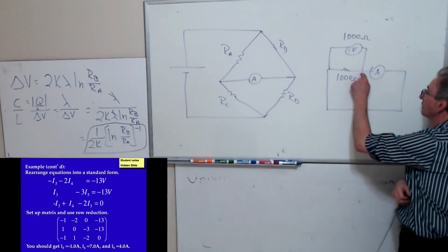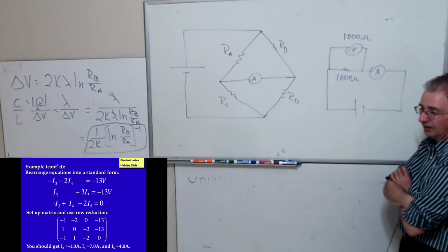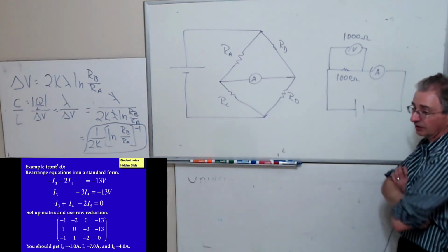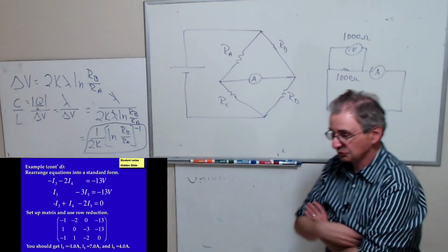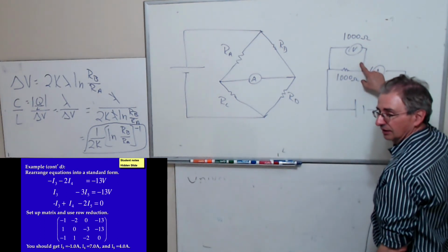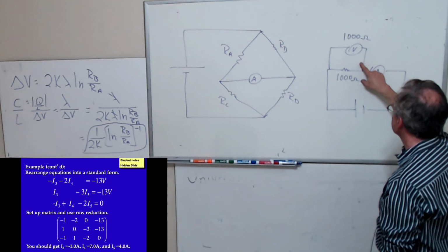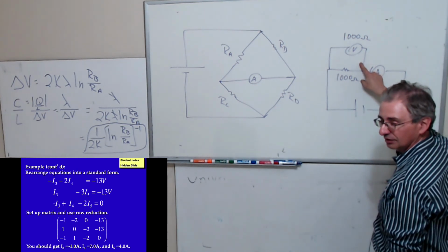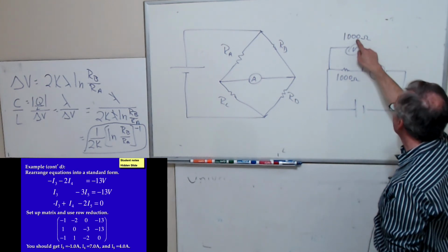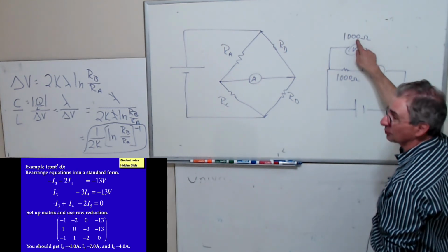And if you take Engineering 17L, he'll make you do a lab where you actually get to see the effect of the resistance of the meter. This one is so dramatic. Your answer changes by a factor of 2 when you use this voltmeter as opposed to one that has 100 million ohm resistance.